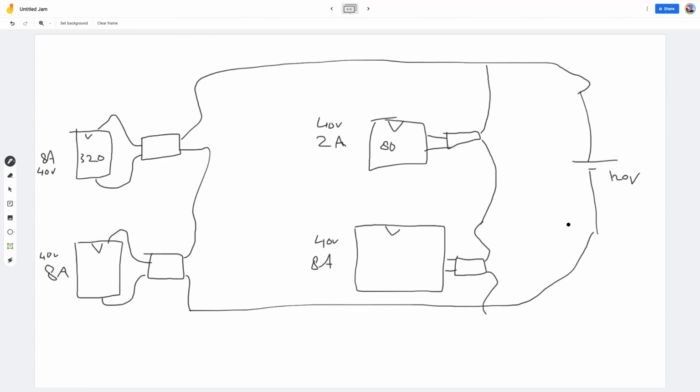So now the left side is going to work well, right? Those 2 MPPTs in series, because they're both equal. So this voltage is going to be half of the battery voltage, just 60 volts. Here you have a power mismatch again, because the top one is 80 watts and the bottom one is 320 watts. We did this mathematics earlier, right? So the total power is going to be 400 watts.